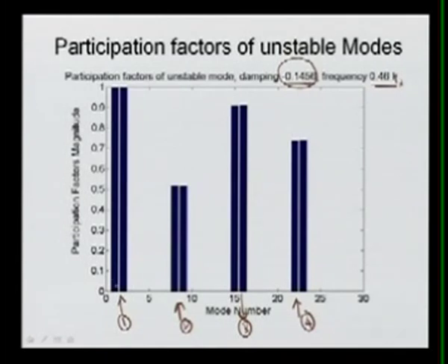You can see that one generator has a 7-state model. So this is up to generator 1, here 14 is generator 2, this is 15, this is 21, and here it is up to 28. This corresponds to the states. You can see the speed participation factor in magnitude, meaning two states are participating: the change in delta and the change in speed.